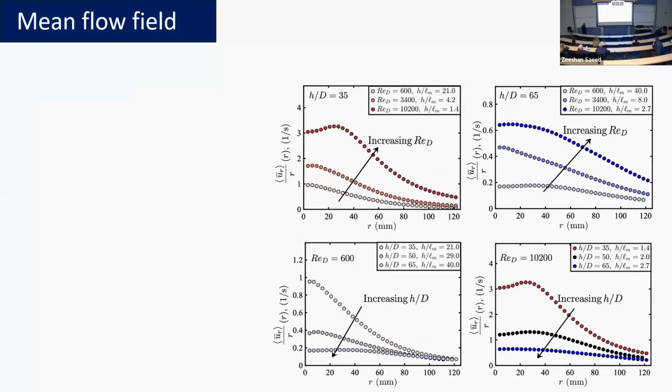With flow in a polar geometry, you also have angular strains that come from radial velocities and radial coordinates. And this is what this is. It's basically the radial velocity divided by the radial coordinate. I've omitted the first data point because that means I'm dividing by zero, and that's a singularity. That's not good, so I'm omitting that, as it would have yielded an unphysical point.